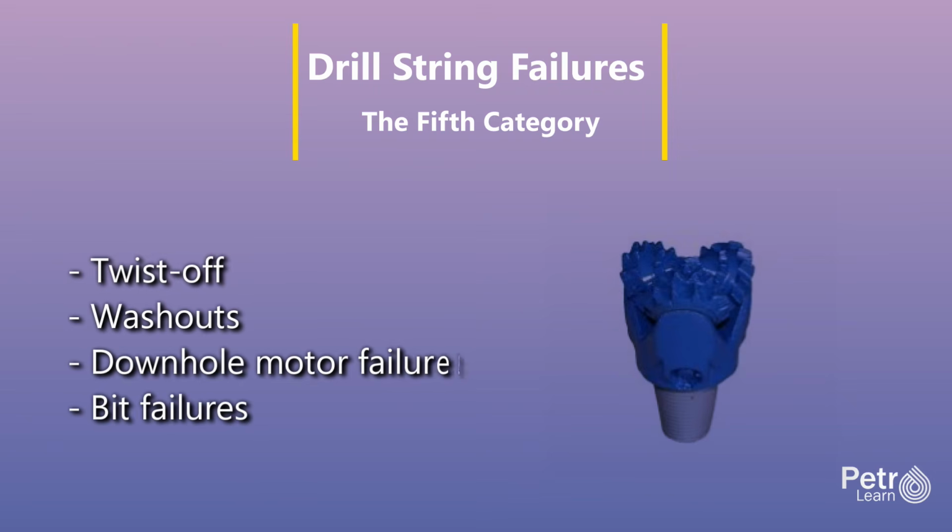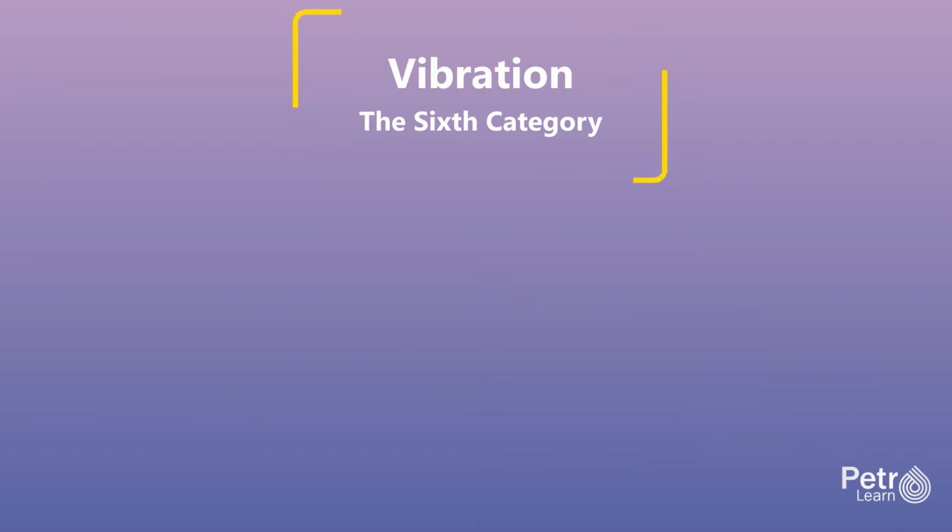Symptoms of impending bit failure generally include a drop in rate of penetration, rising torque, changes in vibration levels, erratic standpipe pressure, and inconsistent weight on bit response. Proper bit selection, real-time drilling optimization, and maintaining correct mud properties are essential to minimize these failures and extend bit life. The sixth category encompasses drilling dysfunctions caused by vibration.